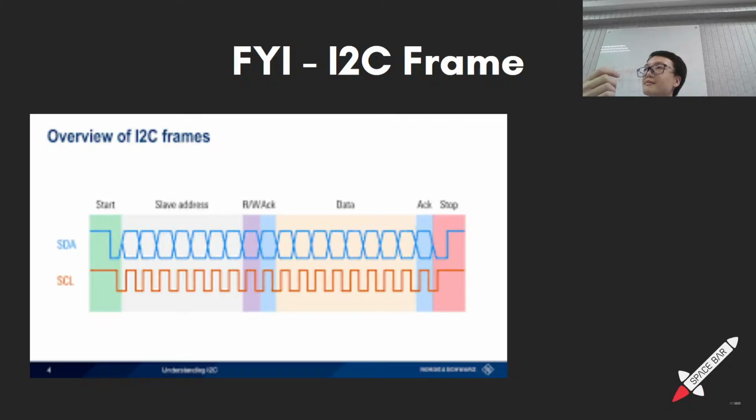With the pull-up resistors, because every device has an open collector output, which I mentioned earlier, high impedance, this whole bus is left floating if you do not put these pull-up resistors, which actually set the voltage to 3.3 volts normally, right?